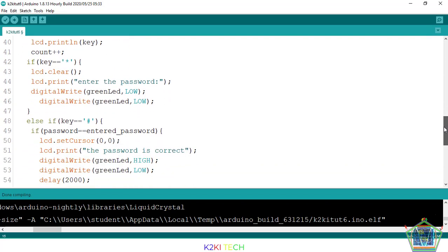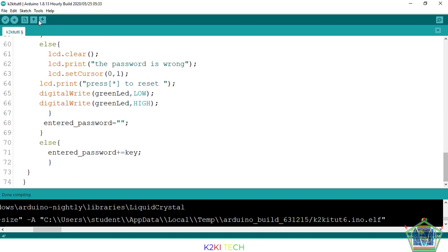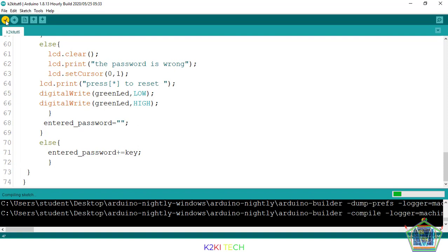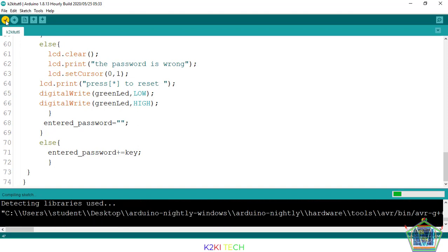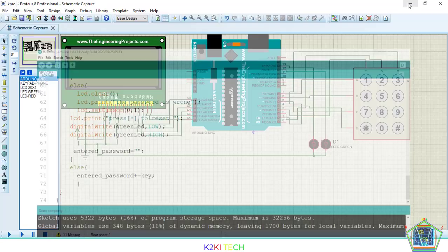After clearing the LCD, set also the count at 0. And of course, compile again and go there to run to see whether it is working correctly, because if the program in Arduino finished to be compiled, of course the Proteus link also will get updated. So it doesn't require to recopy again the file path.